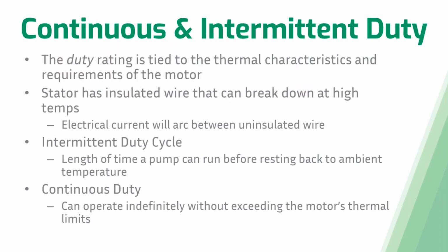So now let's talk about continuous and intermittent duty. Sometimes people tend to use these interchangeably, but there is a major difference. So the duty rating is tied to the thermal characteristics and requirements of the motor. Most motors have stators that have insulated wire that can break down at high temps. And that's just because electrical current will arc between uninsulated wire, which can cause hot spots and cause premature failure.